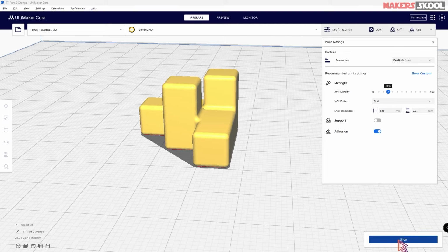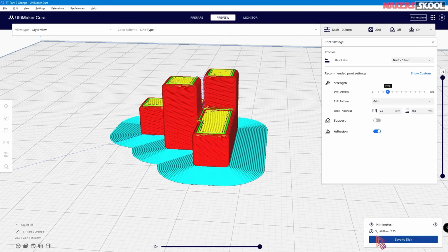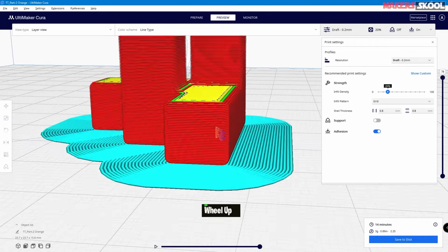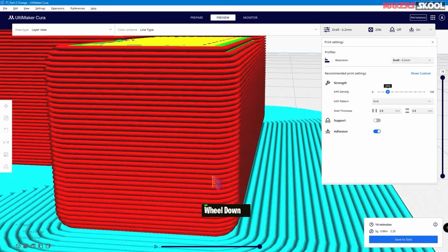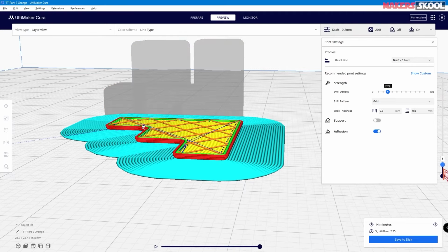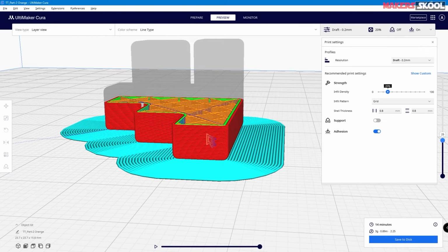When we click slice, and then we click preview, as you can see, the model has been converted into multiple layers, which the 3D printer will print, as seen by 78 layers total, different layers the 3D printer will print on top of one another. This is slicing. Slicing is converting the model into many thin layers, which is used by a 3D printer in the format of G-code.